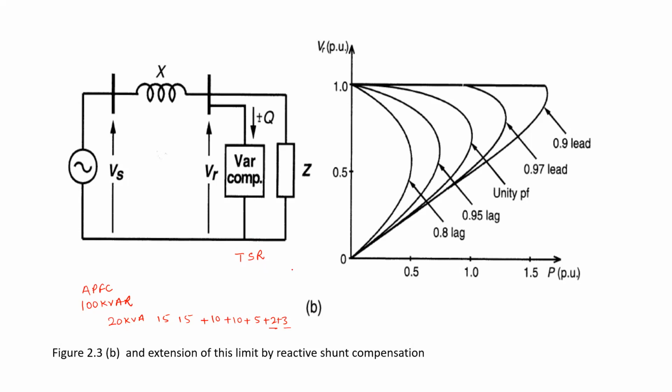So if we entirely replace the contactor by thyristors, it will give the static VAR compensator. So what is the difference from the previous case? Here the voltage profile of the load will remain constant at any power factor. So this is the advantage, and it will avoid the voltage instability in the system.